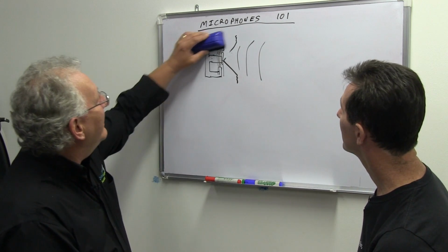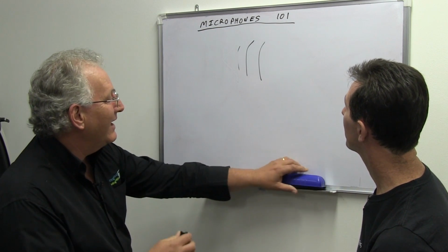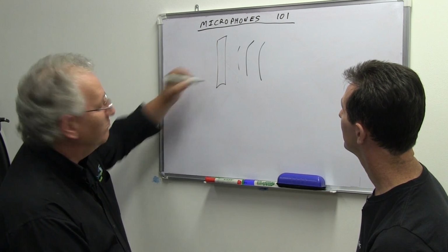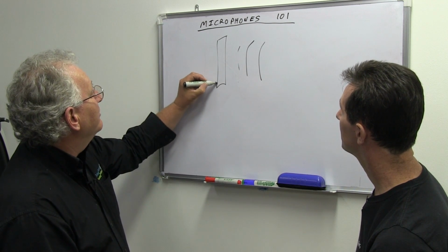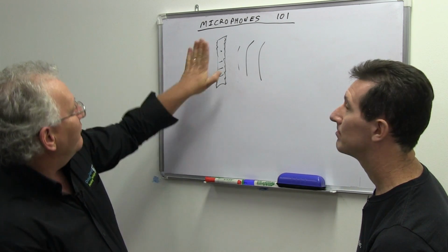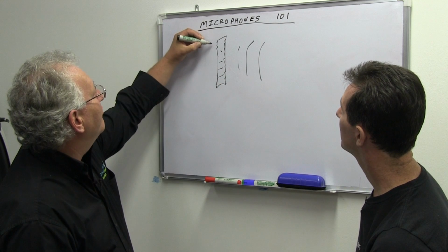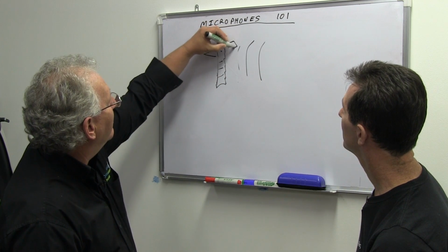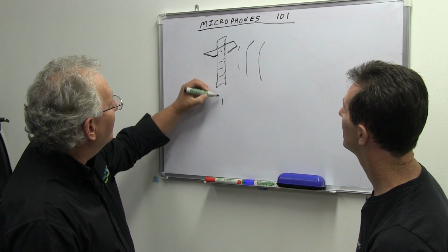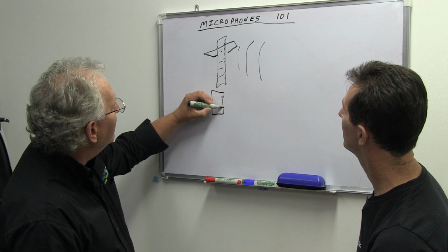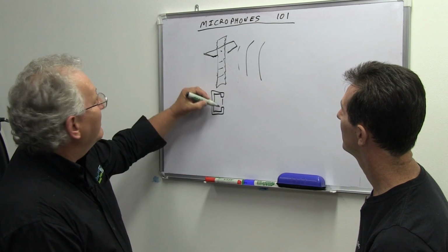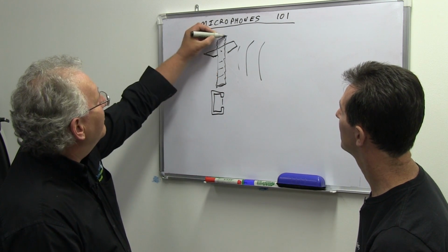Incidentally, there's an interesting variation on that where the diaphragm itself is also the conductor that moves in the field. I'll draw this in 3D: picture a sheet of aluminium, typically corrugated so that the entire length of it is free to flex in and out. Then you put round here a dirty great horseshoe magnet. Looking down from the top, this would be the diaphragm, and you've got this huge magnet around here. As that flexes backwards and forwards in the magnetic field, you're developing a voltage from the bottom to the top.